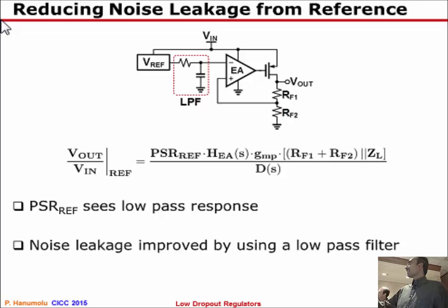So combining the series element with the shunt element, I have sort of hinted this in the context of lowering the output impedance of a buffer, that greatly improves the load transient, because in the end, load transient performance is related to output impedance.